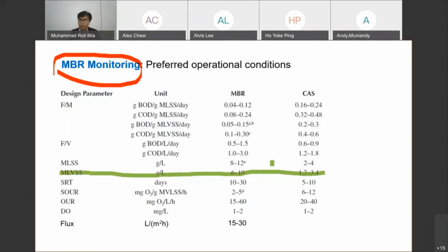Then you can have the highest hydraulic loadings, and at the same time you probably produce less sludge, because when you have a lot of microbes in the system, you have to feed them a lot with the food for the oxidation, and you produce less sludge.